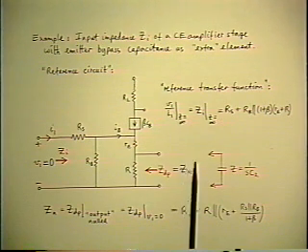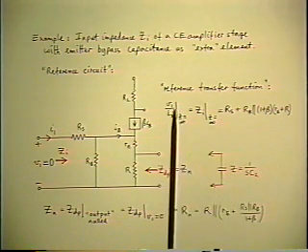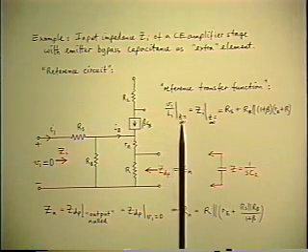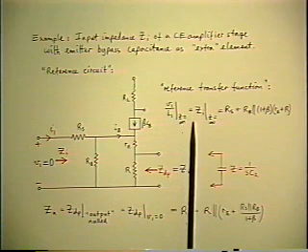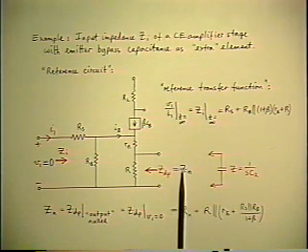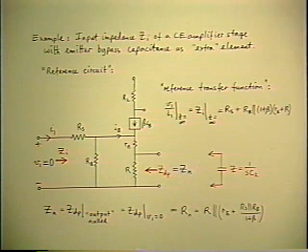So the important point about this example is proper identification of what is the input signal and what is the output signal for the transfer function, so that you can correctly impose the necessary conditions on the calculation of the two driving point impedances. I want to make sure that sinks in for a little bit, because immediately I'm going to make a modification of that.